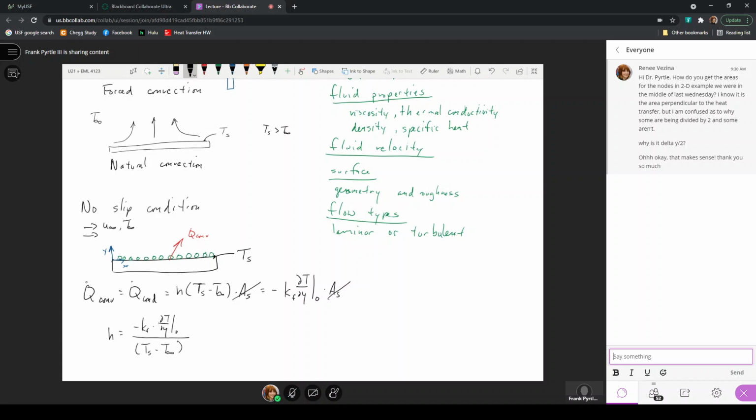such that once we're outside of what is called the thermal boundary layer, dT/dy will be equal to 0, because outside that thermal boundary layer, the temperature everywhere in the fluid will be just the free stream temperature, that is T infinity. So we have to be very specific when we're writing this equality of what's happening right at the surface of this plate here.